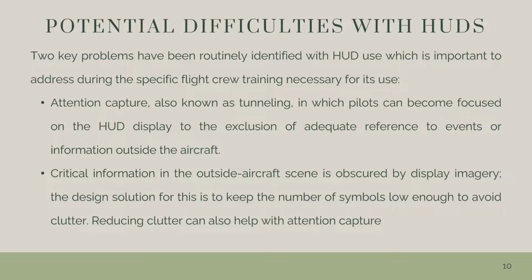Potential difficulties with HUDs. Two key problems have been routinely identified with HUD use, which are important to address during the specific flight crew training necessary for its use. Attention capture, also known as tunneling, in which pilots can become focused on the HUD display to the exclusion of adequate reference to the events or information outside the aircraft.